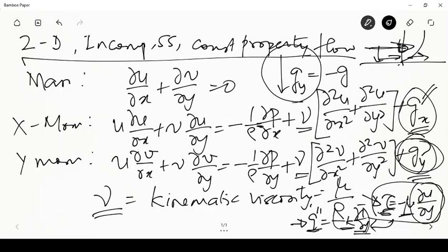The gy actually is shown in this direction, and g is in the downward direction, that's why it's a minus g. So this is basically when the whole substance is present in the gravitational field. When it is present in an electric field or magnetic field, for example, an electrostatic precipitator where particles are attracted by an electrostatic field starting from the corona discharge of a wire, and eventually they migrate towards grounded plates, there the forces would be in terms of the electric field forces rather than the gravitational field forces.